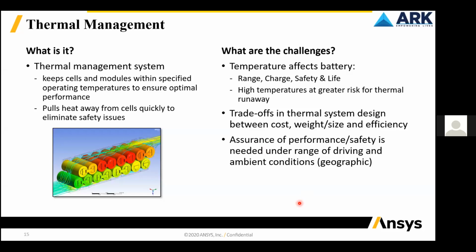So what are the challenges over here? There are various temperature effects in the battery, depending on the range, charge, safety, and life. High temperature creates a greater risk of thermal runaway. Then there are trade-offs in the thermal system design between cost, weight, size, and efficiency.